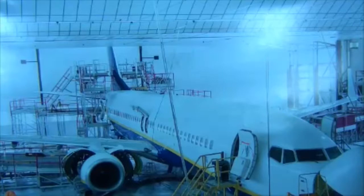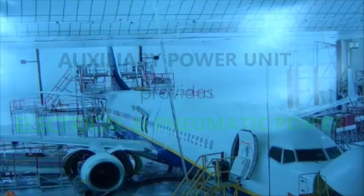Okay, and if there's ever a lack of supply, or insufficient supply of any sort, it's going to have the electrical power be available over the pneumatic power in that case. But as far as in flight, remember, a combination of both is available up to 25,000 feet. Electrical power can be available up to 39,000 feet, but electrical power only.